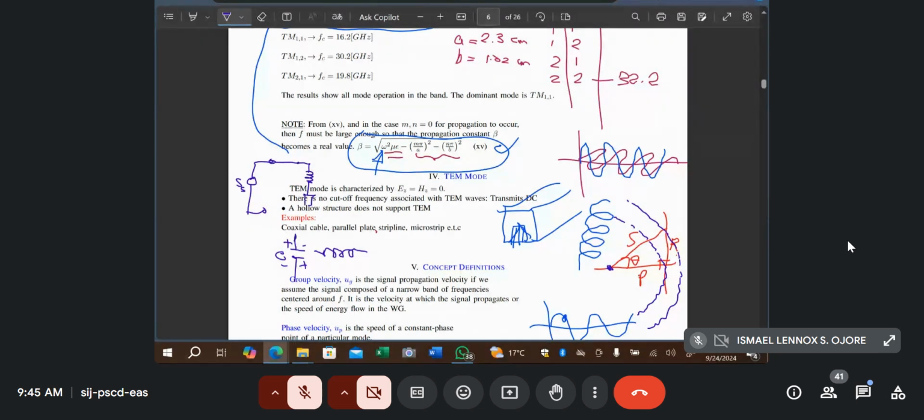Say you have your resistor there. So the resistor will have its P, no problem. Active power will be dissipated. But here, in one cycle, you are retaining power there. It's energizing it. But because you are going to change the phase, the dissipated one remains the same, but this one will now go back. So you're actually sending this power back to the generator.